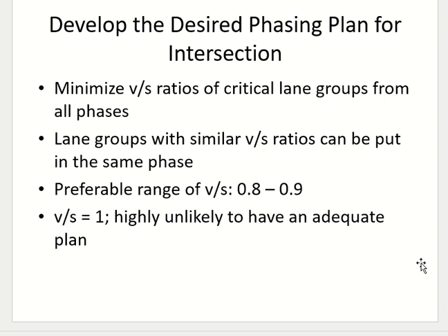More than this is dangerous, dangerous in the sense of traffic flow. You may see very long queues or very long delays. Less than this, that means something is wrong. You are providing signal where maybe it's not required. The volume is too low then. Got it? So this range is considered appropriate. That is what they are saying.